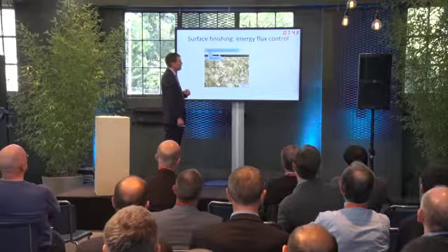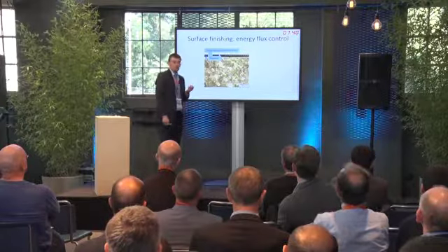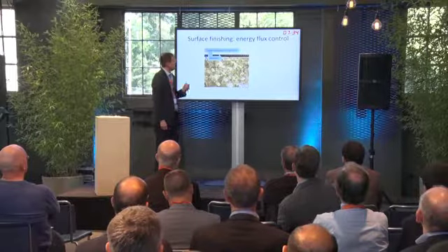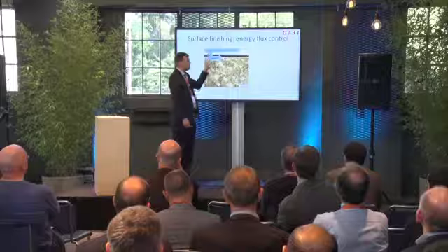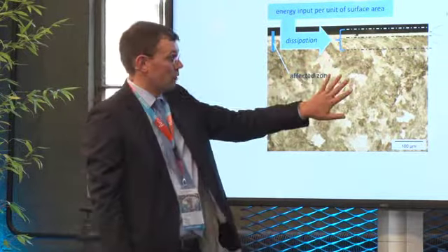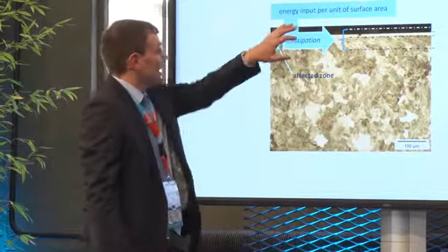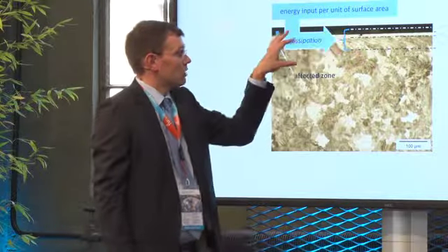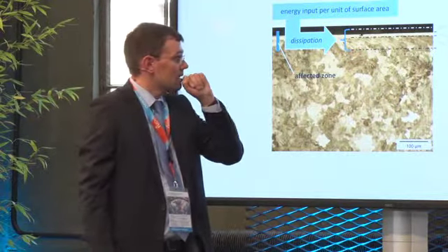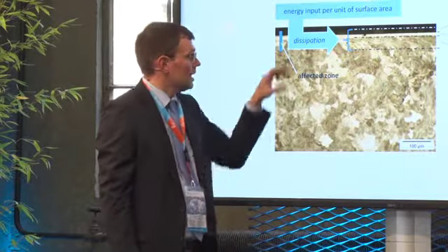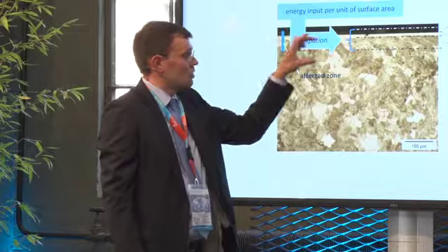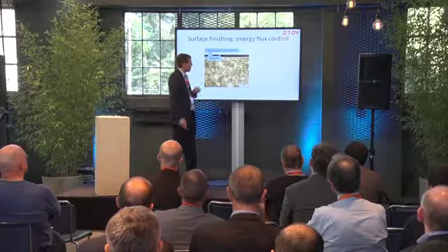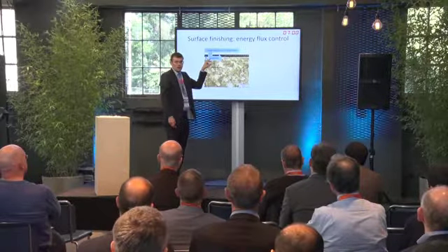One of the ways of looking at this, and in my view, a very efficient way of looking at this, and looking at any surface treatment method, is looking at the energy flux during the treatment process. So if you have here a worn rail, or a damaged rail, whatever, you need to make a certain input of energy per surface area in order to treat the surface. And basically, there are 3 dissipation mechanisms in this top layer which govern the surface conditions after treatment.